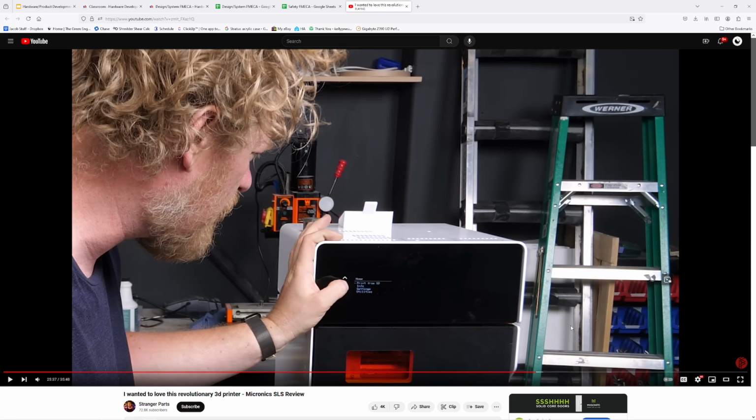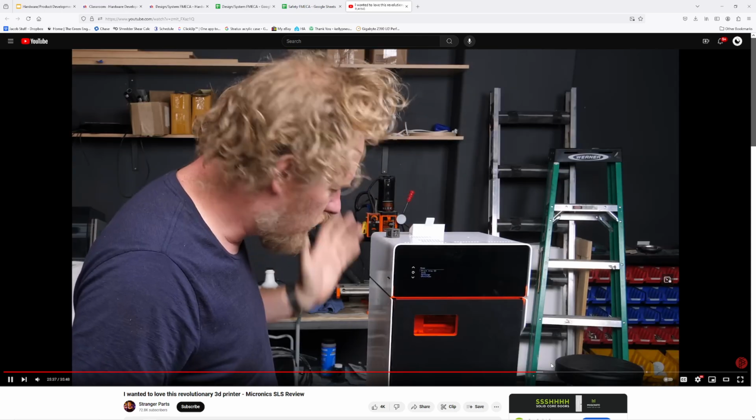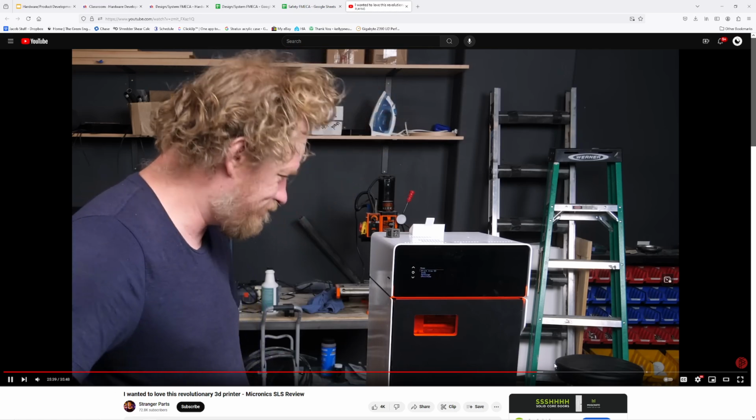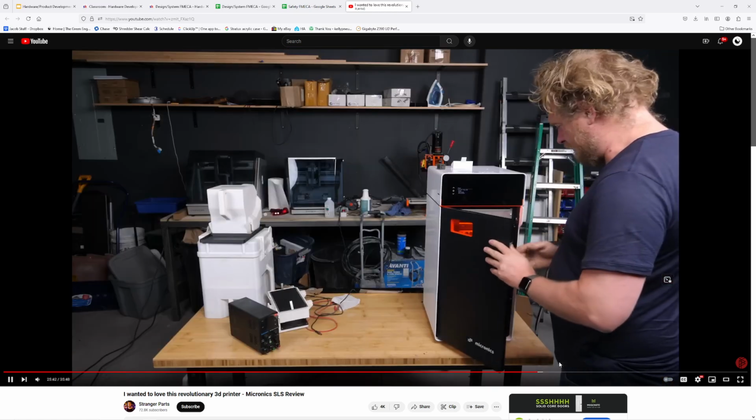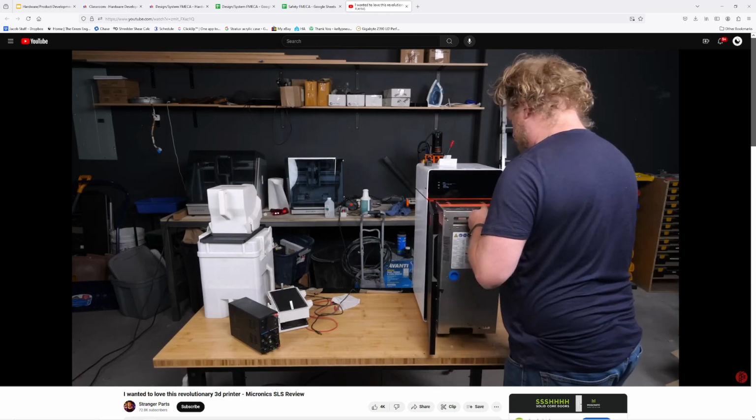So basically, the recoater failed at the 649th spread. Each time it prints, it has that spreader that you saw at the beginning, which will work the powder across and deposit a thin film on the print bed for the laser to sinter. And it seems that now it has thrown a fault error that, hey, I was not able to complete this. And that ends the print. Damn. I don't know what that means.